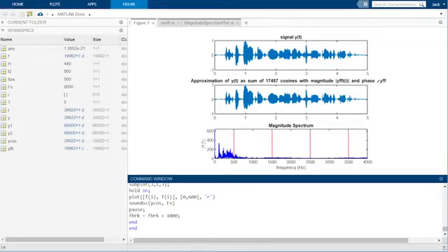We can appreciate that as we add in our high frequency content, we ultimately fully reconstruct our signal from individual frequency components. This demonstration reveals two important concepts. First, it shows that the IFFT provides us the information needed to define the magnitude and phase of each cosine used to represent the signal as a sum of cosines. We showed that by summing cosines using the IFFT, we can reconstruct the signal.